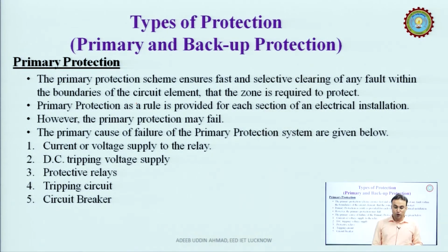The current and voltage supply to the relay may fail, and the DC tripping voltage supply may fail. Maybe there is some breaking of wires, wear and tear of wires, or some loosening of wires. That is why supply failure is very common.